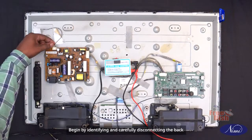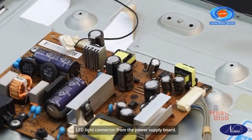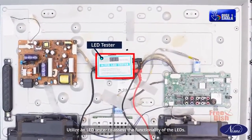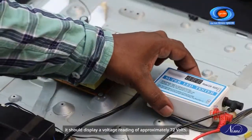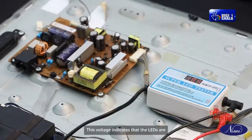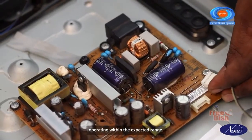Begin by identifying and carefully disconnecting the back LED light connector from the power supply board. Utilize an LED tester to assess the functionality of the LEDs. Ideally, when the LED tester is connected to the backlight, it should display a voltage reading of approximately 72 volts. This voltage indicates that the LEDs are operating within the expected range.